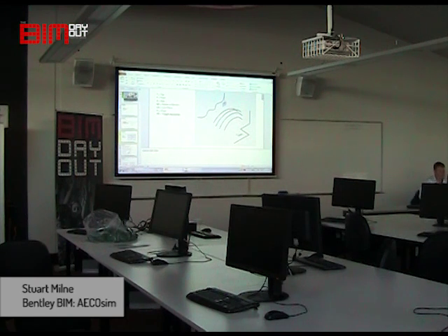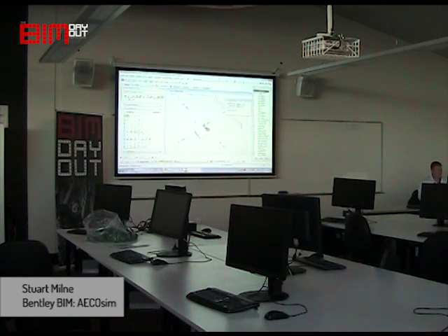So let's say, for example, we then wanted to draw another line, and place the first point out here. We have our compass. Now, as we know, we can do a T, F, and S. That isn't going to satisfy the angle of this thing, is it? So what we can do is type in RE and click on this object once, and you'll see now how the AccuDraw compass rotates itself to be aligned with that object.